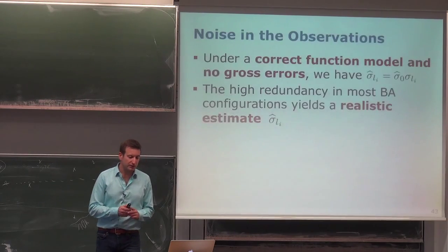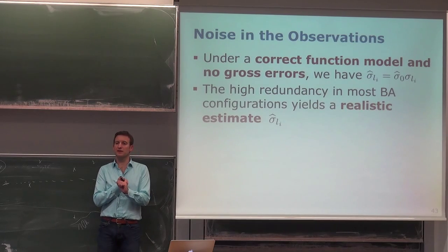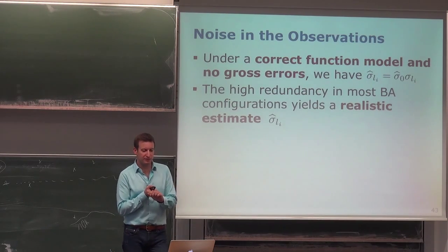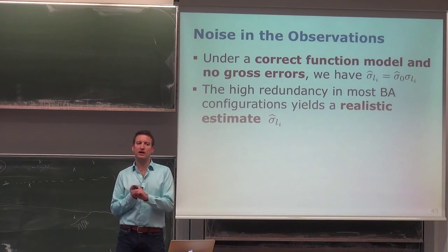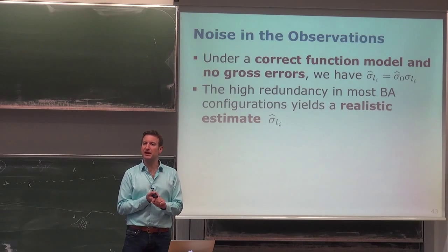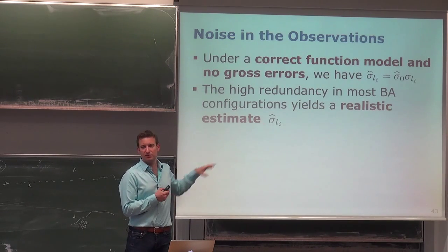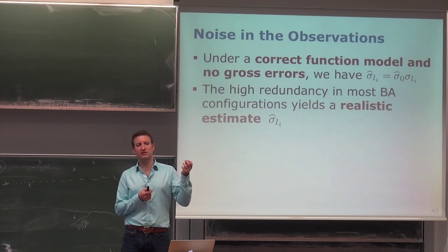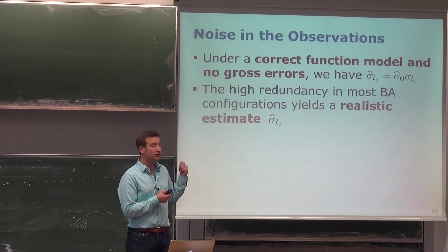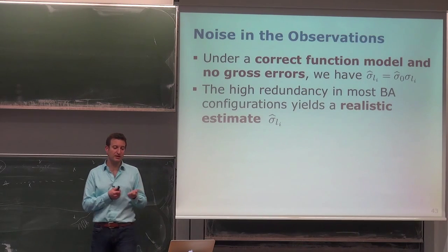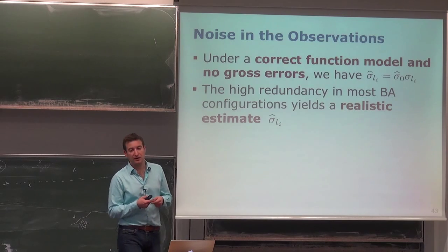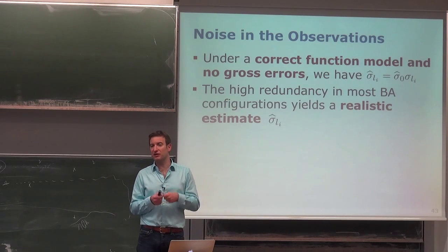Okay, so the key thing is that I can take the variance factor into account to estimate how well my assumptions match what I actually obtain. And this F-test, not assuming that my measurement uncertainty is perfect, is essential in order to make an appropriate evaluation of the result. Otherwise, the null hypothesis will always be rejected. It will always say that the variance factor is too far away from 1 to have a good estimate.